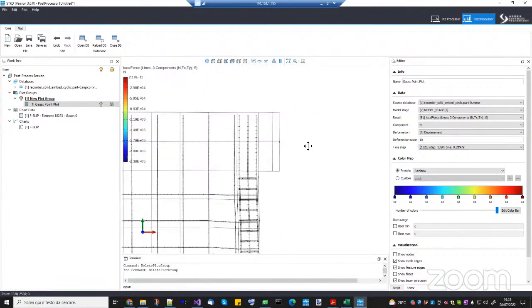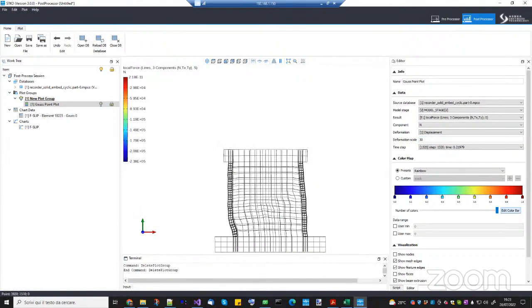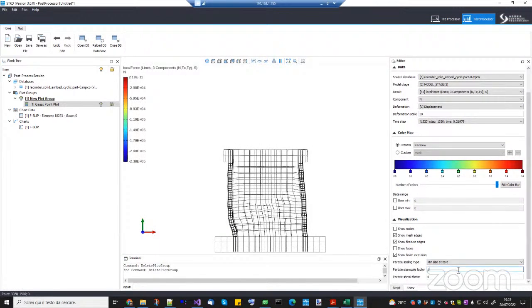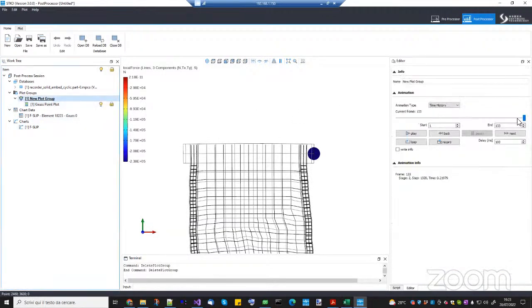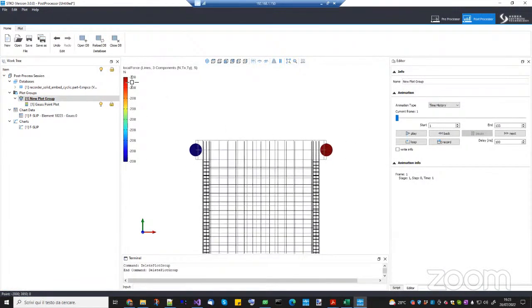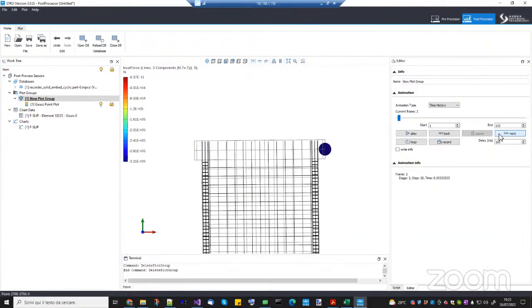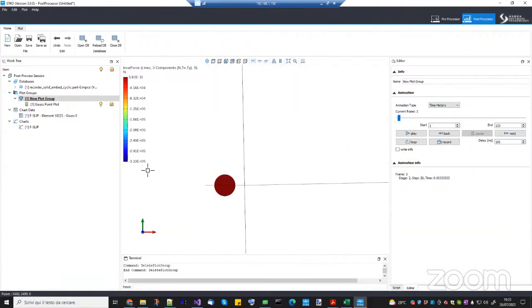Okay, so now it is a Gauss point, which is here. Now we'll make it a little bit larger, and I will increase the deformation a little, so you will also see the separation. Let's say 10. Well, I can put even more. Now you will see that, let's start from the beginning. The very beginning is very low. It's just due to the Poisson effect on both sides. But then when I start, now it is pushing here. So here you have 0, because as you can see, there is a separation.